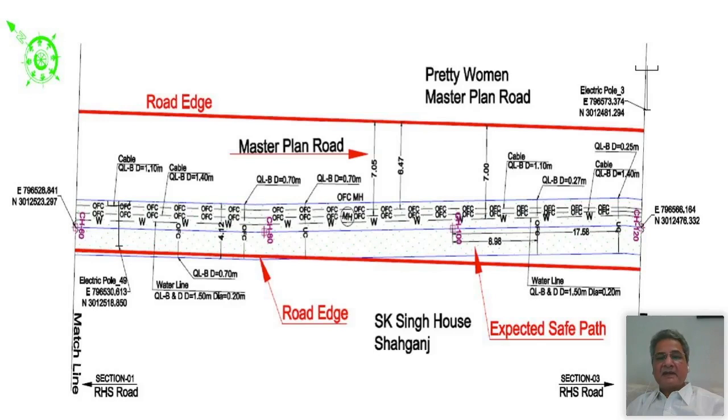Why? Because depth is given there, but diameter also is given, 0.2 meter. Now this diameter information has come from background information, quality level D information. Because as I told you, neither induction locator nor GPR gives you diameter. So this information has come from background information. So this is how a SUE map looks like. So now, once you receive a map, it is written on the forehead: 100% reliable, 75% reliable, 50% reliable, or not reliable.